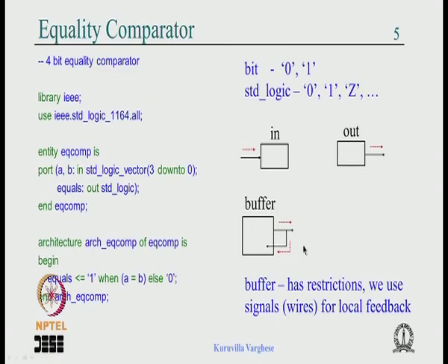Now there is one other direction specification, which is nothing but in out, or an IO. That is not the same as buffer. In the case of buffer it is still an output, the pin is an output, but there is a tapping which is used internally, okay.